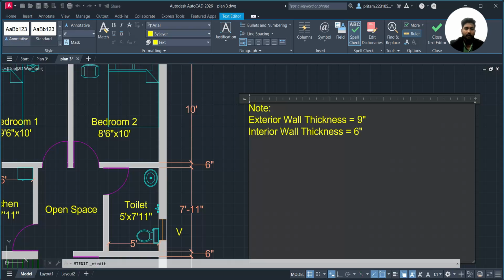Then after we will be seeing the further part of the dimension. Here we have added two types of doors, D1 and D2. So D1 size we have taken here as 3 feet. Okay, the D2 size we have taken as 2 feet 6 inches, and the window size, there are basically three types of window, W1, W2 and V, that is the ventilators. Just put here, and we will be putting here as 2 feet. Then for the window 2 it was about 4 feet.